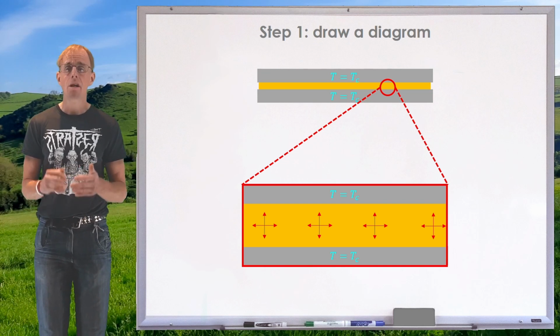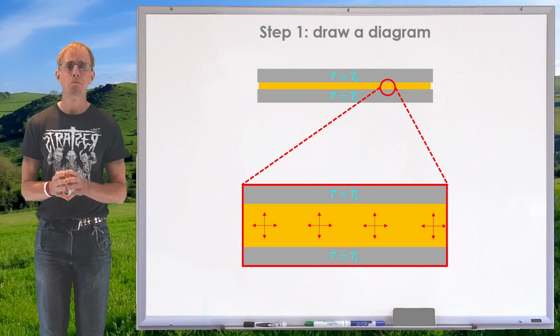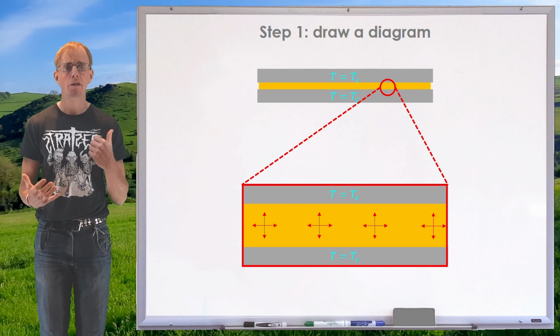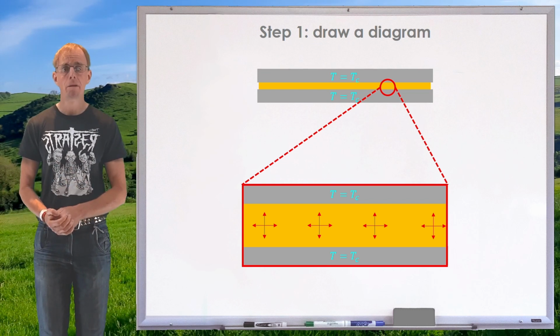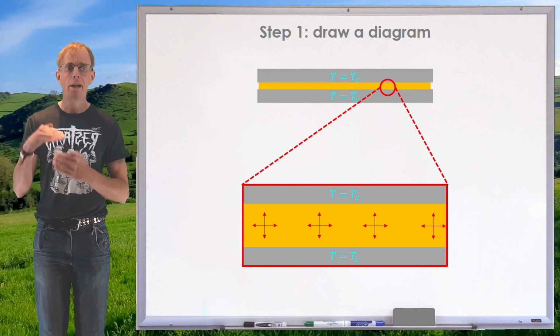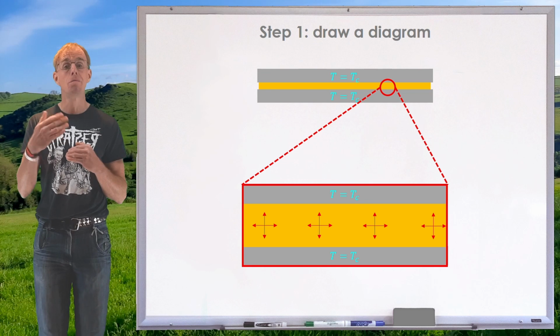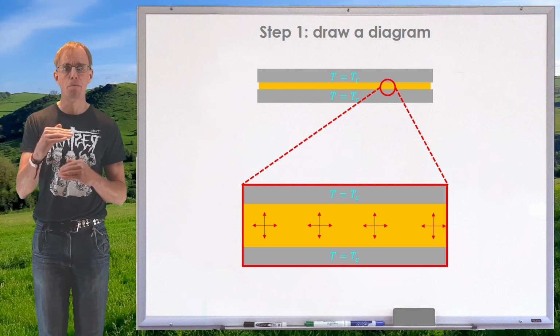So the only thing from a heat transfer mechanism point of view that dominates is heat conduction in the bulk of the polymer. So we have a purely conduction-based problem of a molten polymer in a mould where we're assuming perfect heat transfer from the polymer to the mould, where we can instantaneously change the mould temperature.